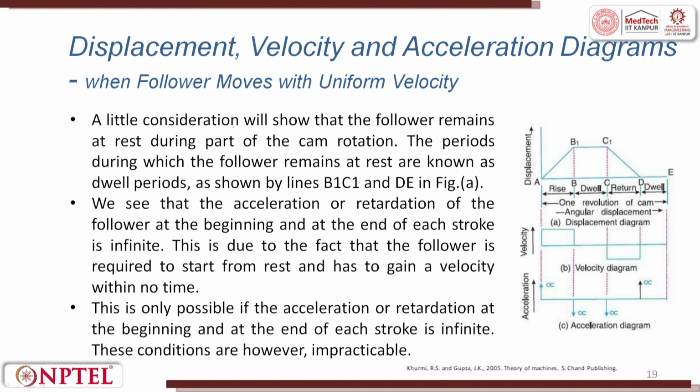A little consideration is needed while showing that the follower remains at rest during part of the cam rotation. The periods during which the follower remains at rest are known as dwell periods, or at the highest peak. So, it is as shown in B to B1, C1 to C and again D to E.